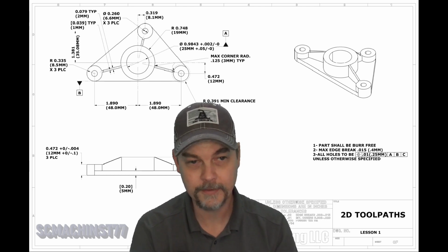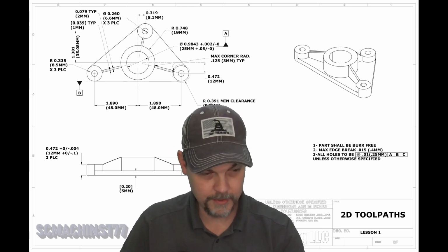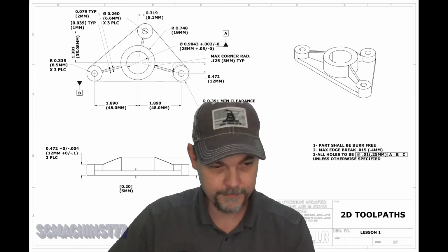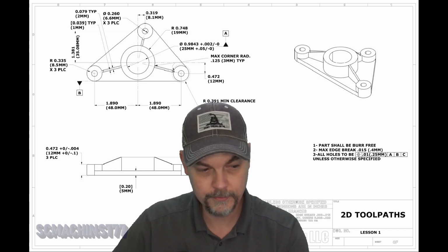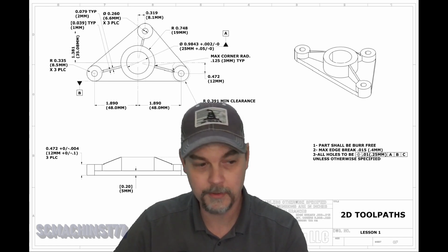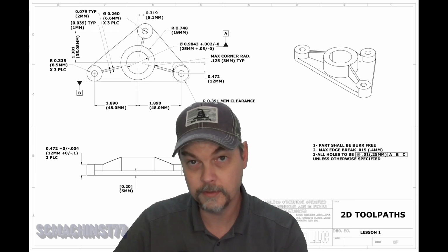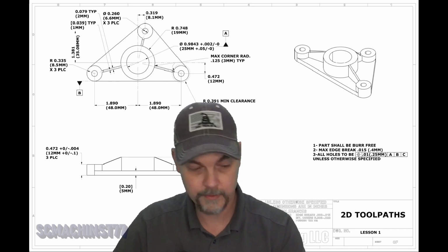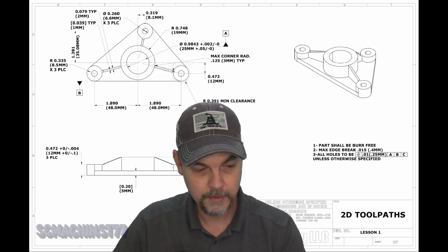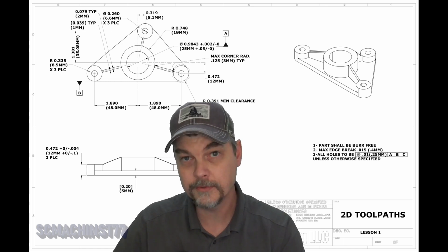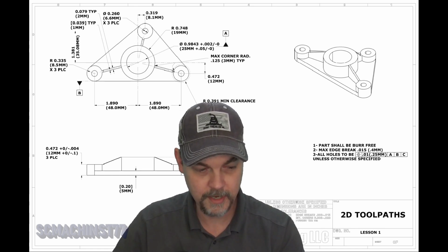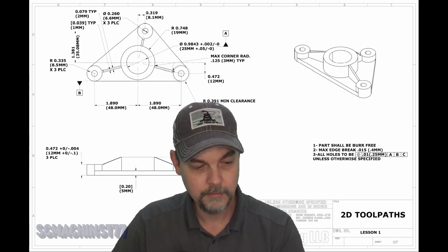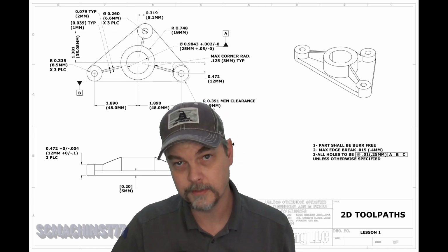What's up, everybody? Welcome back. This will be video 3 of our 2D Toolpaths lesson 1. In the previous videos we came up with a rough process on how to machine the part, selected our tools, selected the machine in Mastercam, went over how to create or edit tools. We created some op-on geometry, and we faced the stock using a facing toolpath, left 50 thousandths, and we machined 2 edges to hold on to for our next operation.